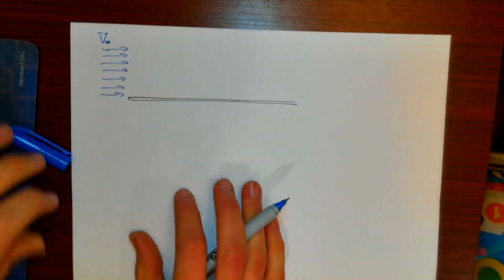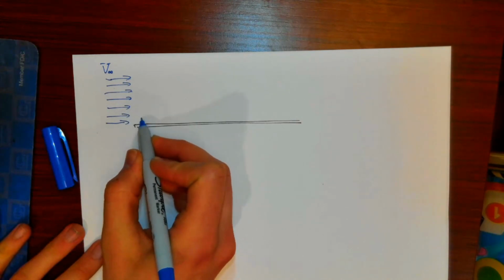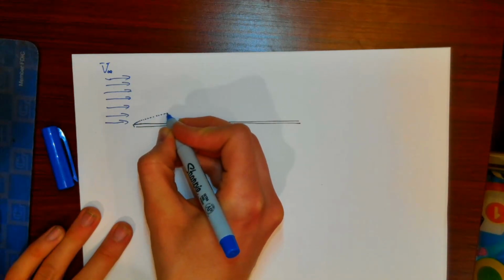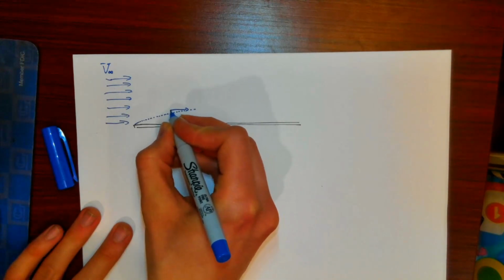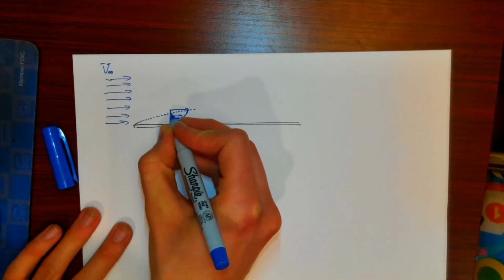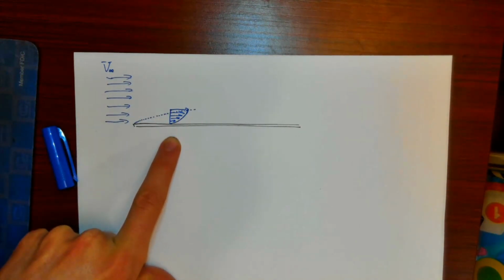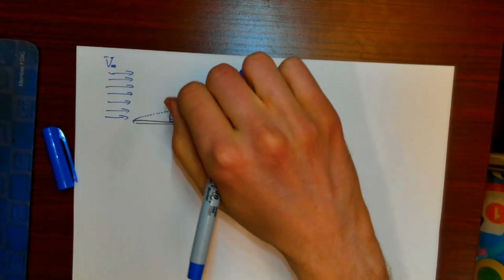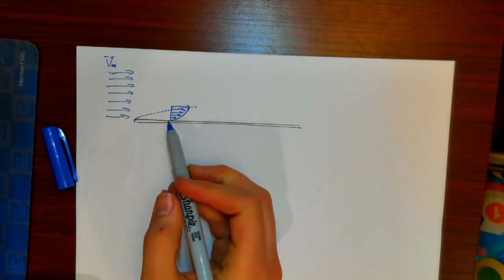And if we looked at the hydrodynamic boundary layer, we said, hey, this fluid that comes in stops once it gets to that plate, and some of that flow basically gets redirected up. There's this boundary layer that basically grows, and the fluid transitions from the free stream velocity just outside the boundary layer all the way down to zero velocity right at the plate. So the boundary layer is basically this transition between free stream velocity and zero velocity down at the plate.